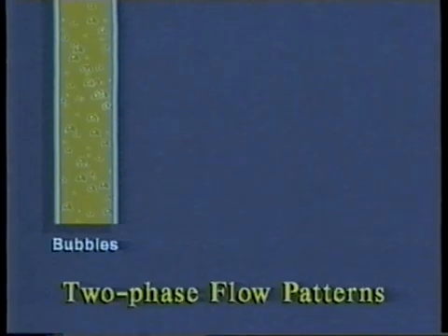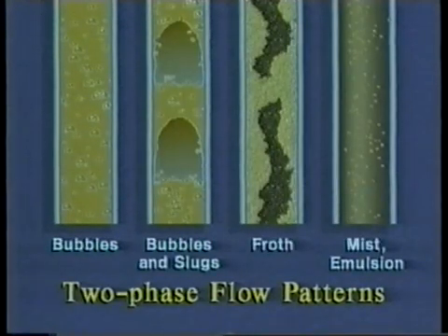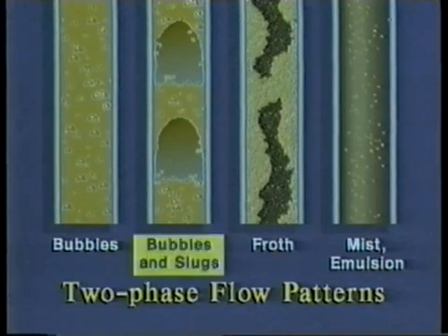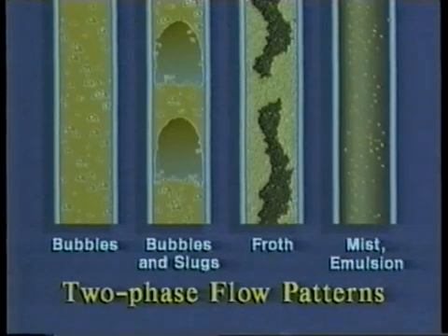If the flow is water and oil, a bubble flow regime is most common. When gas and liquid are present, the flow is much more complex. Bubble flow probably exists up to a condition of about 10% gas by volume. A transition then quickly occurs to slug or more complex flow patterns. Unlike oil-water flow, gas-liquid flow is very turbulent and violent and produces a very complex response in the flow meter. As a result, gas-liquid flows can be difficult to measure accurately.